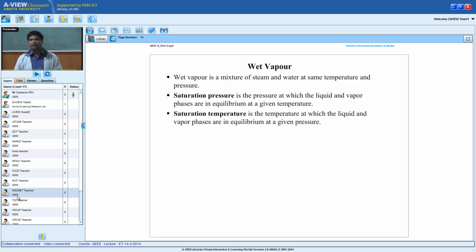See the knowledge. For water, there is a combination of pressure and temperature which can produce both. Otherwise it is impossible. And if I change the substance, the relation changes. At the same pressure, saturation temperature will be different for different substances. What does it mean? How will this knowledge help me? What is the use of changing my substance from water to something else? Do I get extra benefits? That is where the thinking and innovation start coming. The saturation pressure is a function of saturation temperature and vice versa.